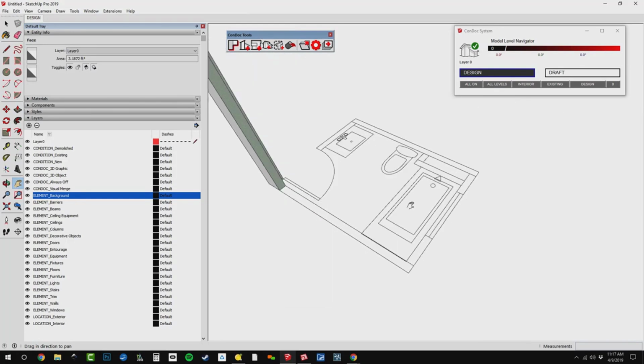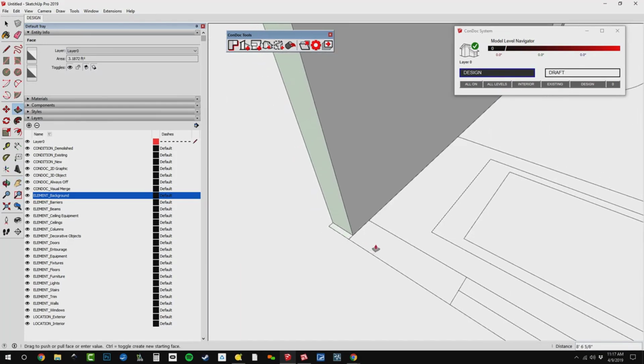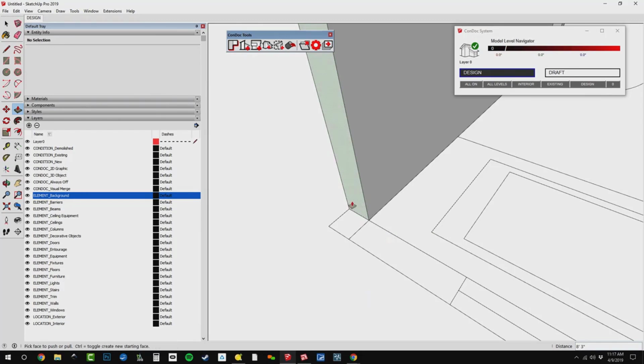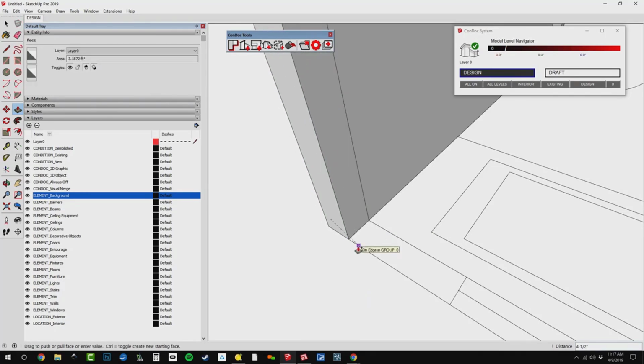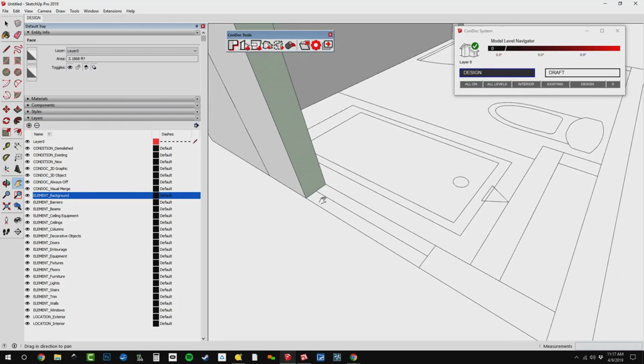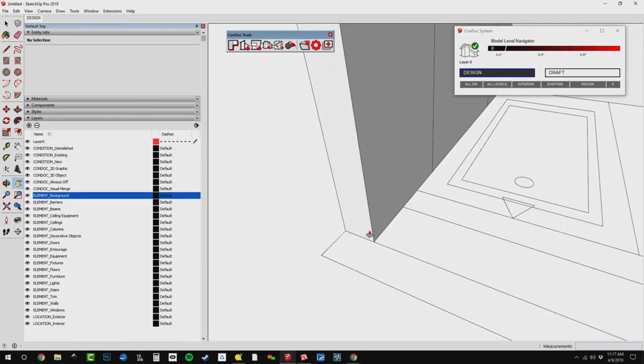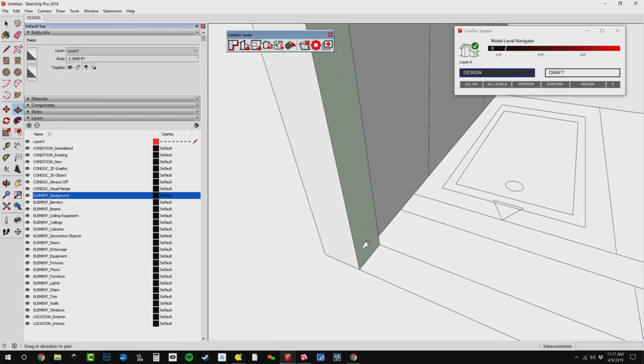All right, so let's just keep doing this, and I'm going to navigate to that view that's strategic for what I'm working on. And the hotspot of that push-pull tool is the tip of the red arrow. I'll click there, start another one, tap Control, that's Option on the Mac. All right, and so here we go. Now I can really start flying through this to make all this 3D geometry come to life, like that.